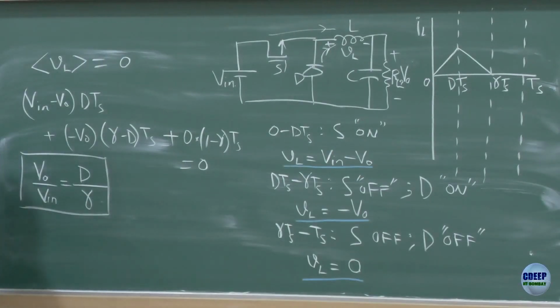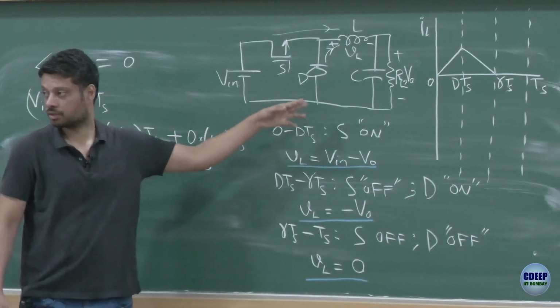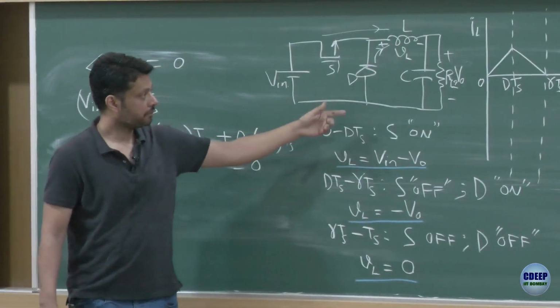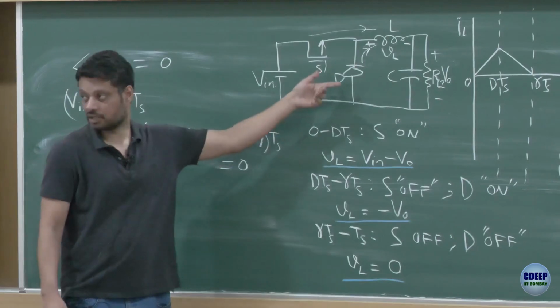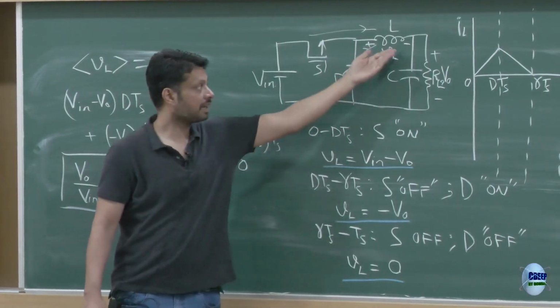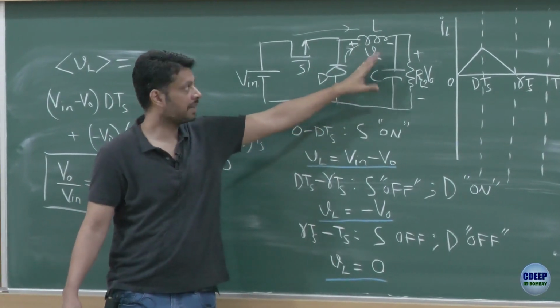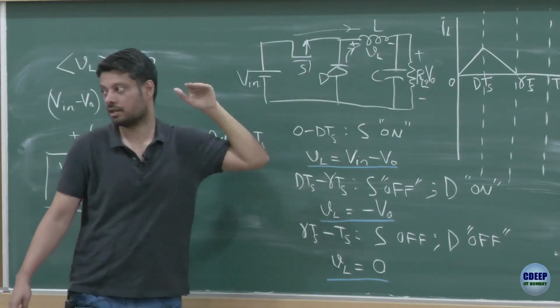Okay, so you asked me the question whether I can repeat the part where the diode turns off, right? So in the second period, the diode is on, right? So the equivalent circuit is just this one. You have an inductor, you have a voltage which is almost a stiff voltage source, which is applying minus VO. Inductor current is falling.